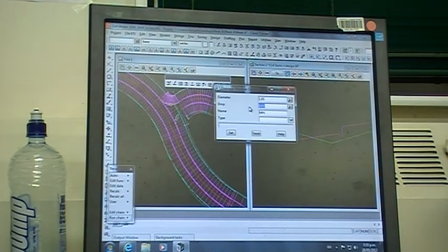The next one is the drop through the manhole. We set the drop to allow for head loss. Now the standard default here is 20 mils through the manhole. Most councils now require a minimum of 30. I always set it to 50 mils minimum unless I get into real problems with grade.